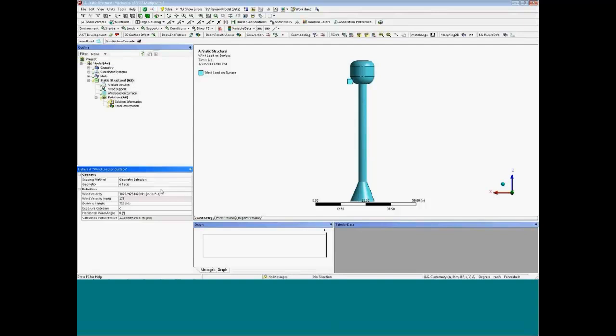And in here, one of the nice things is that you can see units are associated with these different inputs. This is not something that is associated with a command block. You could certainly do this with a command block, but if you changed the units to a different system and then solved, the command block no longer matches up. So this keeps track of all that. It'll do the conversion for you. You can put little drop-downs in here, whatever you need to do for that boundary condition.